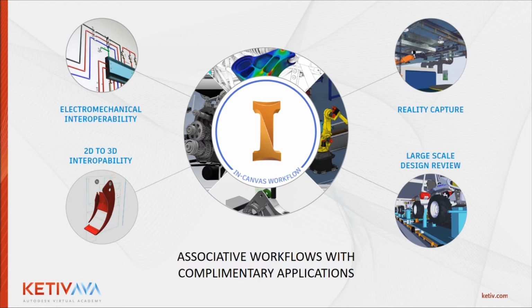And lastly there is Navisworks, which is a viewer where you can do walkthroughs, right? A lot of people ask, can I do a walkthrough of my facility? Can I do a VR walkthrough of my facility? Some of that is becoming realer now that these tools are becoming more capable of such things. So in Navisworks, you can perform large-scale design reviews. You can send this to people who aren't necessarily CAD users, and you can use collision detection to figure out, is this factory layout actually going to work? Are these two things going to collide when my boom arm comes all the way around?